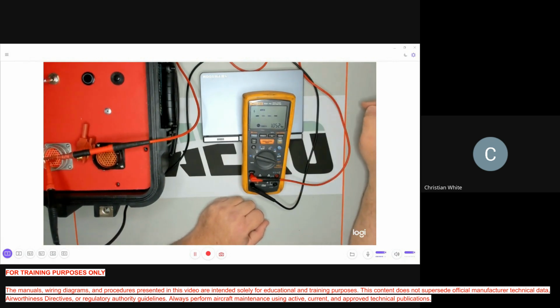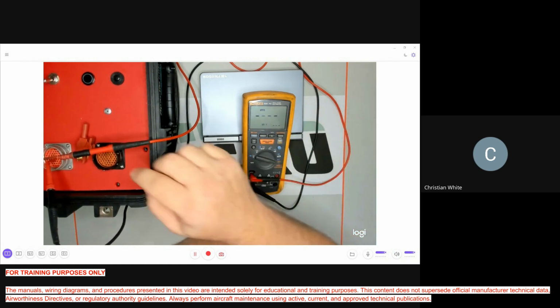I'm going to turn it on. The most you're going to see at 1,000, a perfect score, is 2.2 gigaohms. Okay, so I'm not seeing anything there at all. Again, give it about 10 seconds to make sure, but that looks good to go. So let's see what a bad reading looks like.